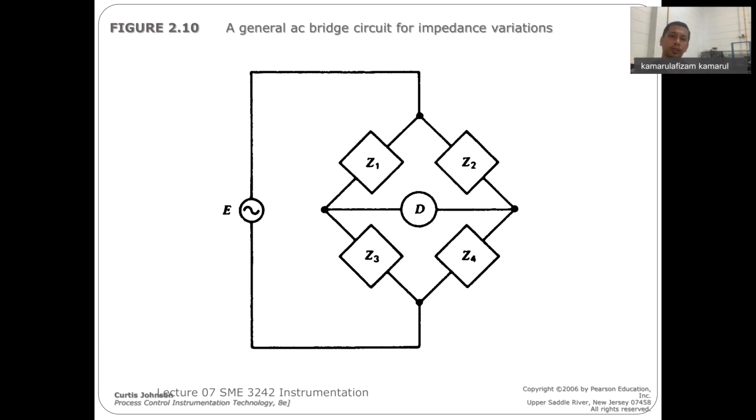They produce variation, and you have changes in the parameters that you are measuring. The sensor will put out some kind of change or variation in terms of impedance, which you can always measure. You put the sensors in the configuration of a Wheatstone bridge, and you can potentially detect the voltage output D here in this diagram, which corresponds directly to the input Z3 or Z4.